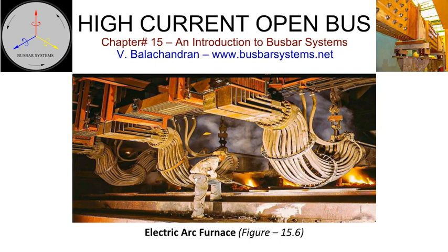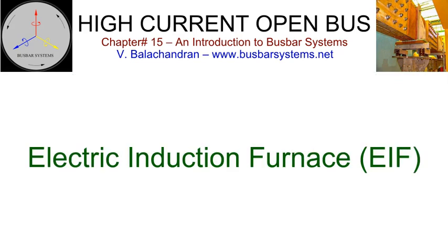The connection between the furnace transformer to the end of the cable is carried out by a rigid conductor. These are kept as short as possible. The flexible connection between the furnace terminals and the rigid conductor comprises several water-cooled, silicon-rubber insulated, braided copper conductor cables, connected in parallel.